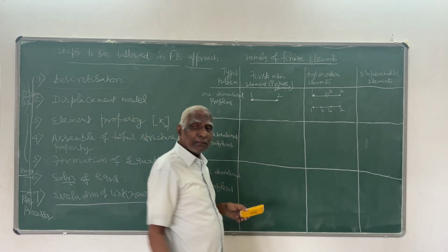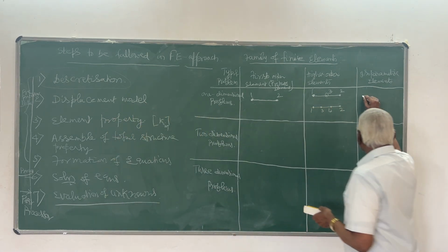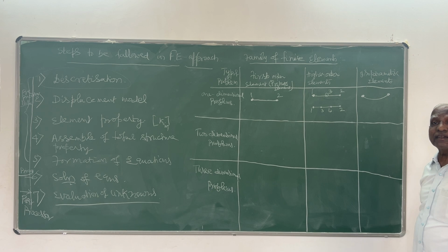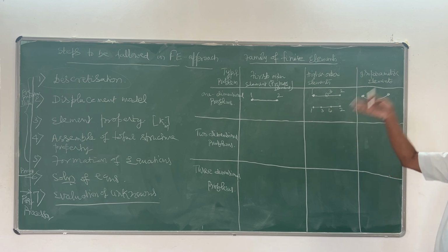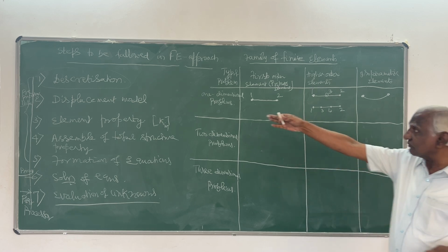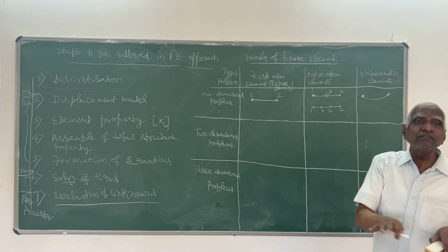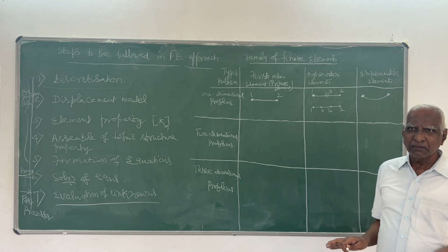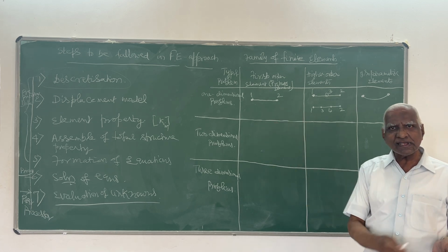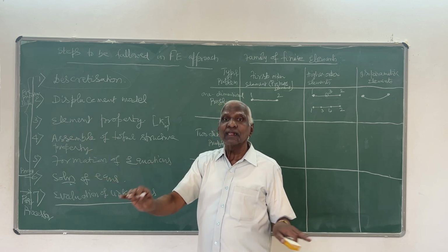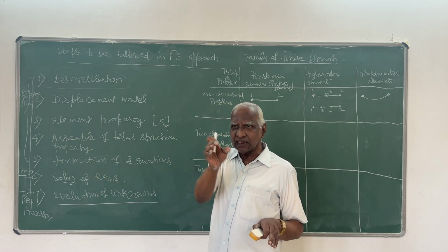So in isoparametric type of elements, to take care of your curved boundaries, whatever the element you need, that is called isoparametric element. To define the geometry, whatever the parametric functions we are choosing here for displacement, same functions we choose for defining geometry also. That is called isoparametric element. In the primary element, the displacement model will be represented by certain equation, with certain parameters called shape functions.